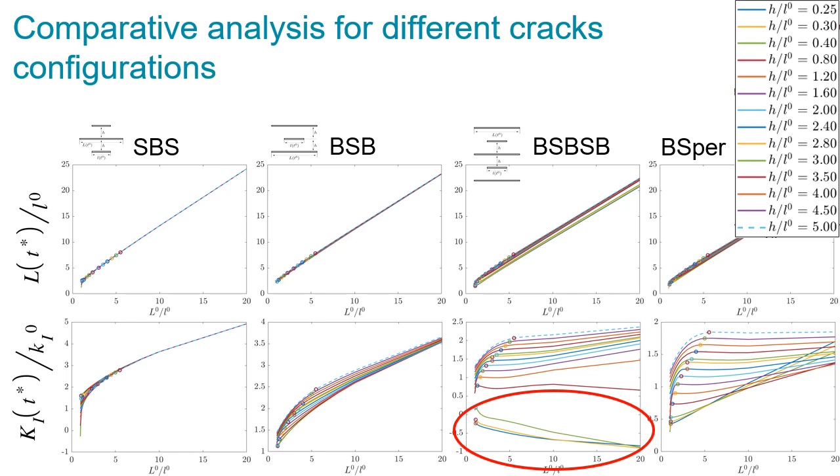The most interesting thing, however, is that the dependencies of stress intensity factors for the central big cracks in the arrays consisting of 5 cracks and in periodic arrays turned out to be qualitatively different for relatively small distances between the cracks. Look at the 3 lowest lines. This graph was expected to be somewhat intermediate between the neighboring configurations, and it really is for large distances between the cracks, but not for relatively small distances.